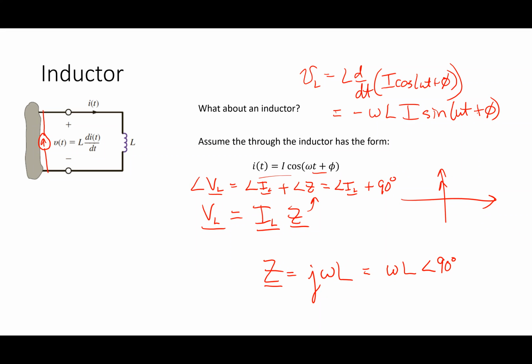This approach is used to figure out the steady state solution when I have sinusoidal sources. If I only care about the steady state solution when I have sinusoidal sources, I can use impedance. That just so happens to be a really important thing, because like I said, we have sine waves in audio circuits and in power circuits and radio, so all these places it comes into play.